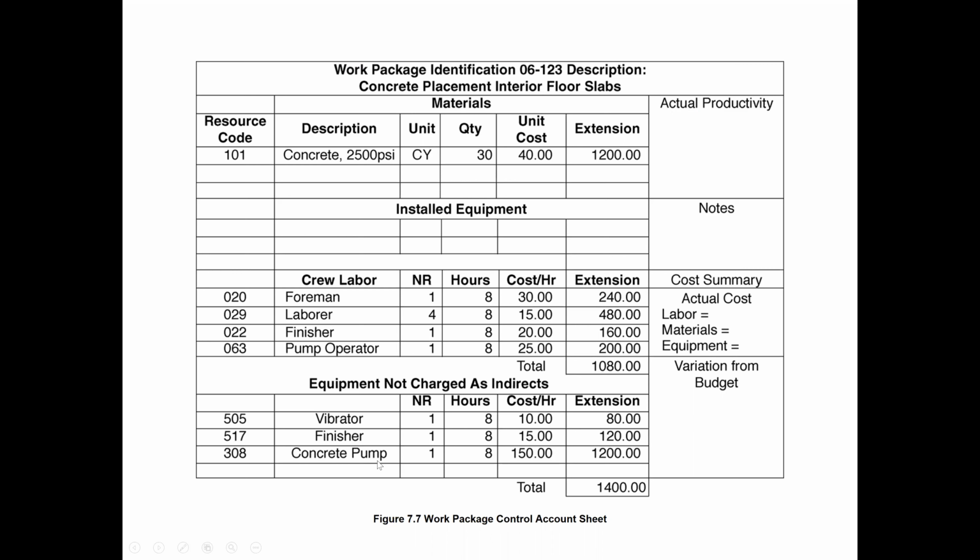So at the end, when we keep these codes, we can see how much, for example code 101, the total cost for completion. This will add up, and at the end we will know the cost in each head, how much material we have used and how much its cost is. These kinds of things are very helpful in the next projects. You know how much the labor cost was, how much the material cost was, and how much the cost for the equipment was in this project. So we can compare the actual with our planning, and it will help us to control the cost.